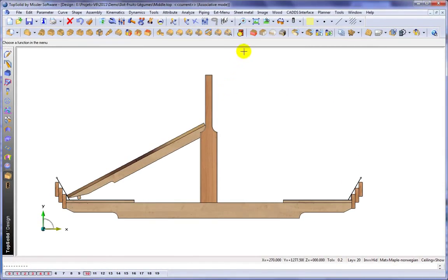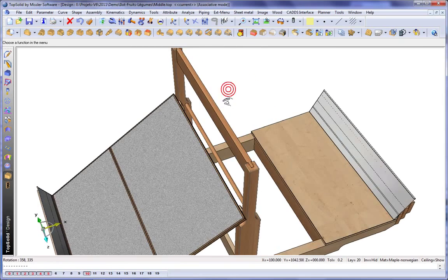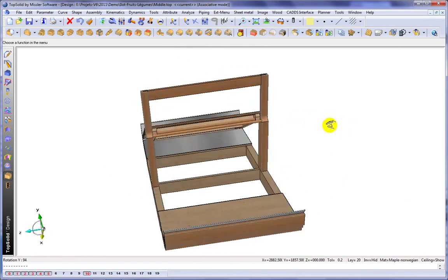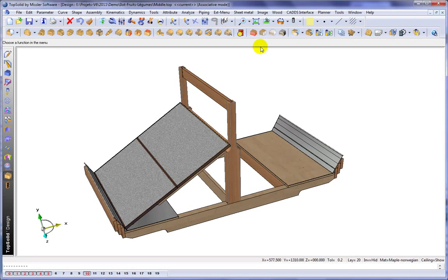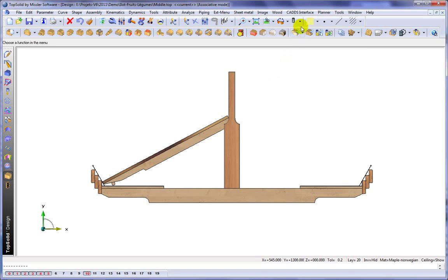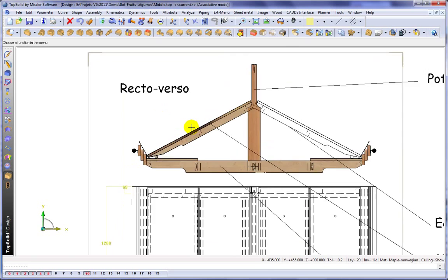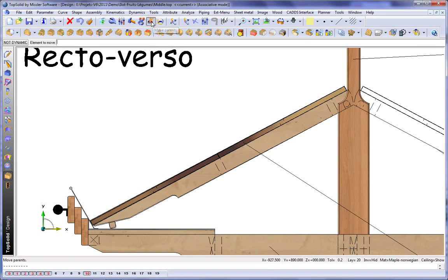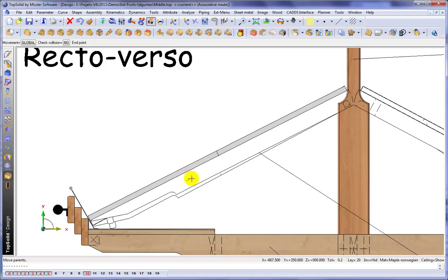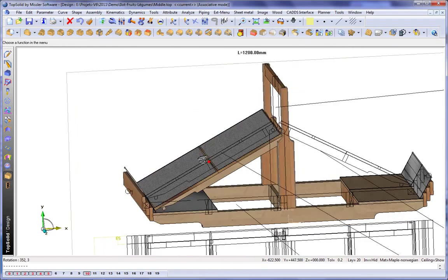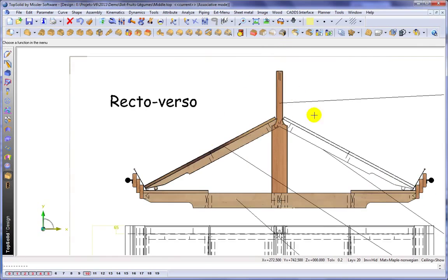Okay, so we've created in another design the roof section that attaches to this. And you can see that here. The reason we created it as another design is because this way we can test it in our assembly. So we have added that roof design to this design using a bottom-up assembly strategy. You can see it looks perfect. And moreover, we can test it. There's supposed to be a degree of freedom there, and there is. That's perfect. It's an advantage of using bottom-up assemblies.